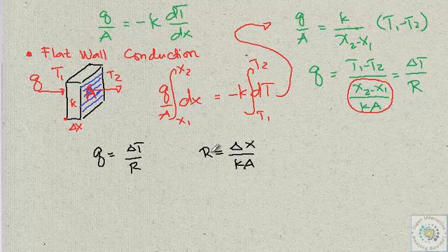And this is not that difficult to memorize really. Resistance could just be thought of as the resistance to flow, meaning it resists the flow. Well, if the slab is thick, it offers a lot of resistance. And if it's a big area, then heat could flow through a bigger area, so it could have a free flow of heat through there because the area is big. That's why area is in the denominator, because it reduces the thermal resistance.